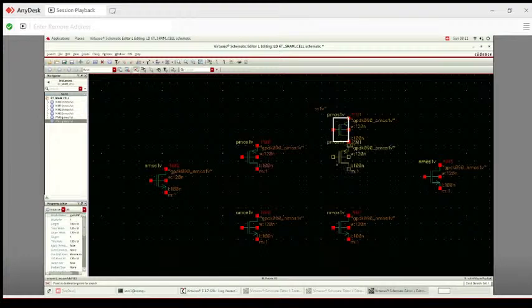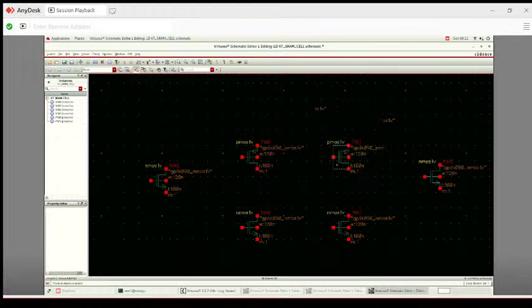Here we align both PMOS with NMOS. Okay, so alignment is done. Let's connect them to form an inverter. So firstly we will connect the drain of PMOS with the drain of NMOS. Let me connect it. So this, our first inverter, is done.